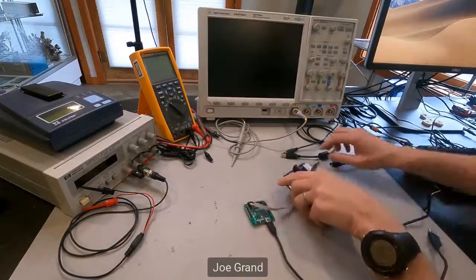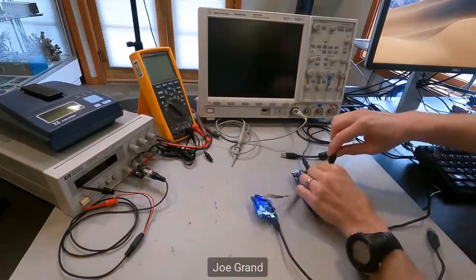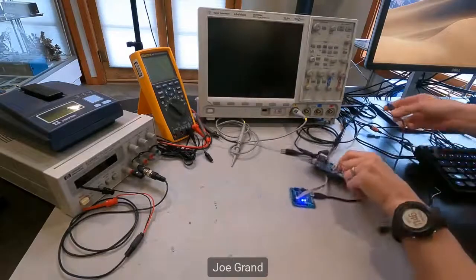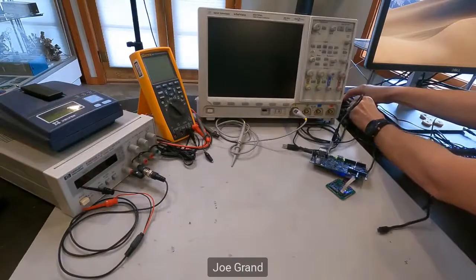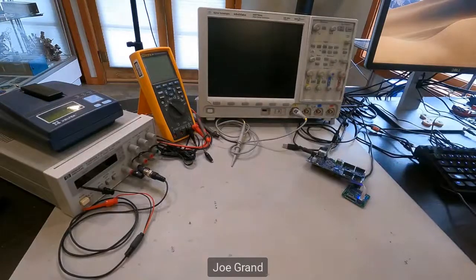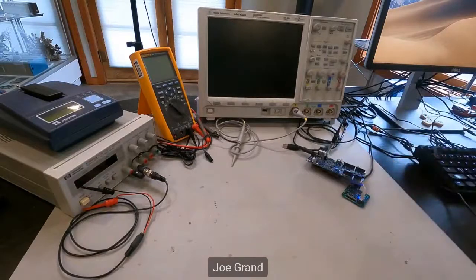So we have our device here. I'm going to plug it in. I have another FTDI friend connected to the UART interface. And then I need to get the Tigard plugged in as well. So this is kind of going to be off the screen a little bit. So Tigard is our JTAG interface, and then our FTDI friend is the UART interface. I like to think of the UART as kind of the front door and JTAG as the back door. All right, so I'm going to share my screen again.